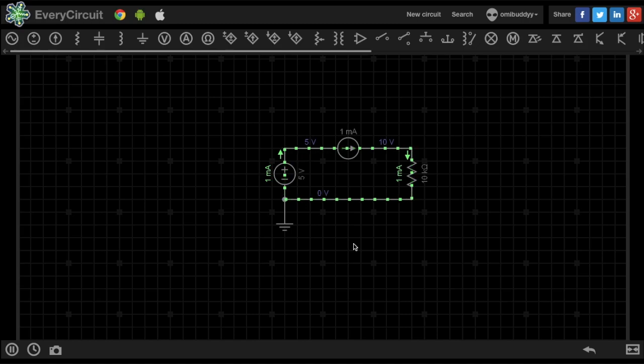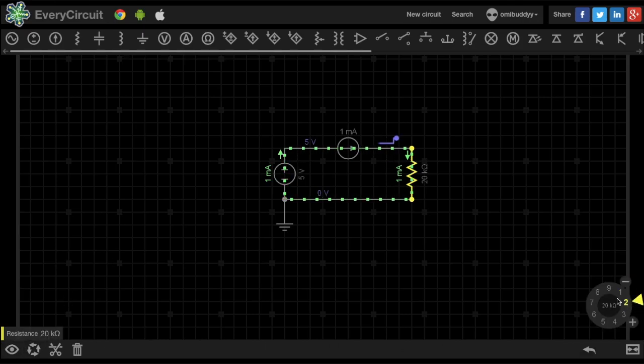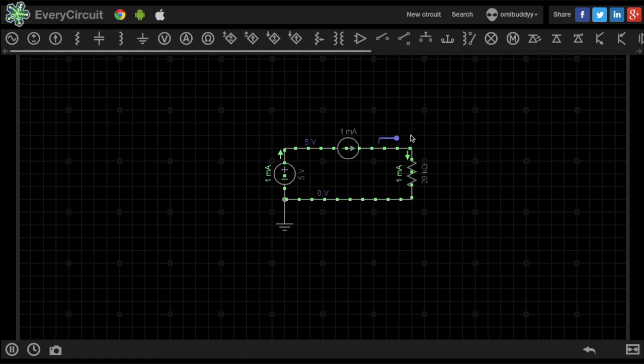Now let's try if current sources can give us gain. And you can see with the use of a current source we are able to get the gain. This is possible because now the circuit current is only governed by the current source, and by dumping the current in the load resistor we are able to get the voltage at the output as we want. It is also clear that if we change the value of load resistance R2, we will be able to change the gain of the circuit. As you can see, as I change the load resistance, the output is also changing.